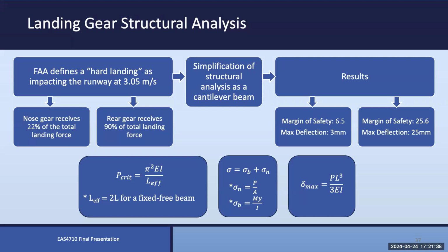So that PL cubed over 3EI is great for an isotropic material, but when you're looking at composites, things get a little more complicated. So just be aware of that. Not to say that you did a bad job. When you have a 0/45/90 layup with equal fibers in all four of those directions, you can start treating things as isotropic and get back to that type of equation, but your modulus isn't going to be just the modulus of a 0-degree fiber anymore. It'll be less than that.